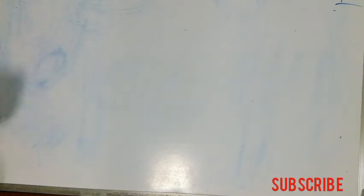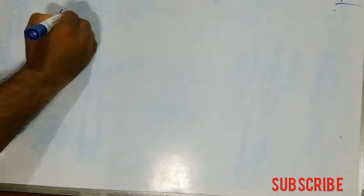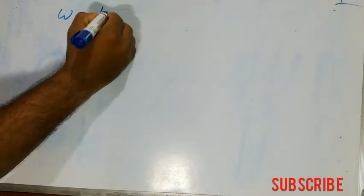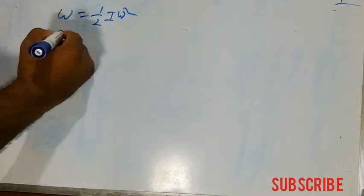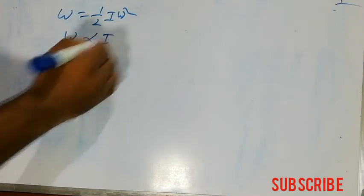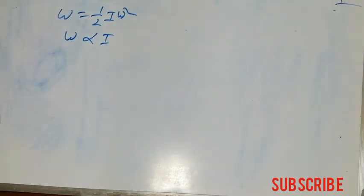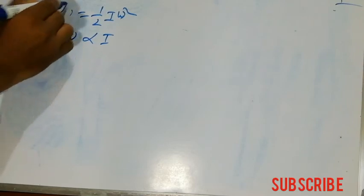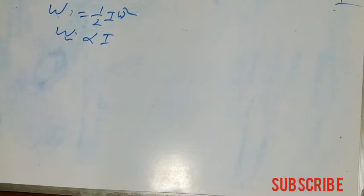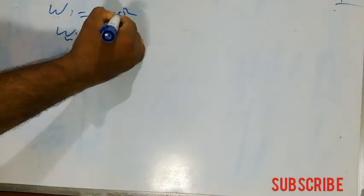So work done, we know that work done is equal to change in kinetic energy, that is half I omega square. Final rotational kinetic energy becomes 0 as it stopped. So the work done is proportional to I, as omega is fixed.